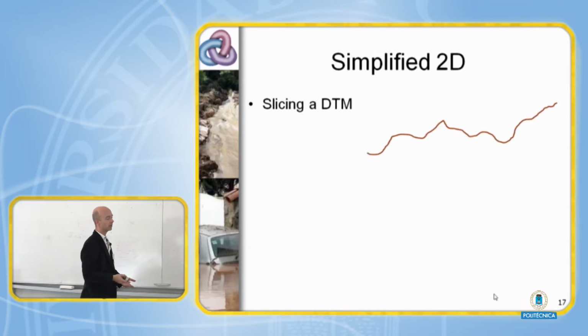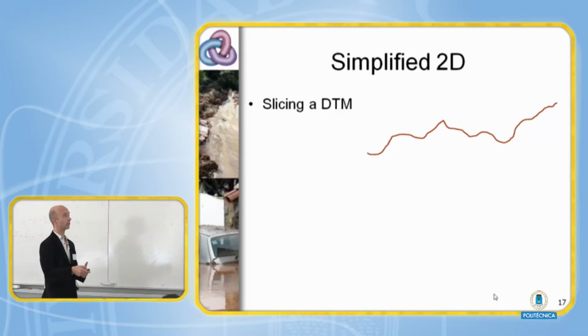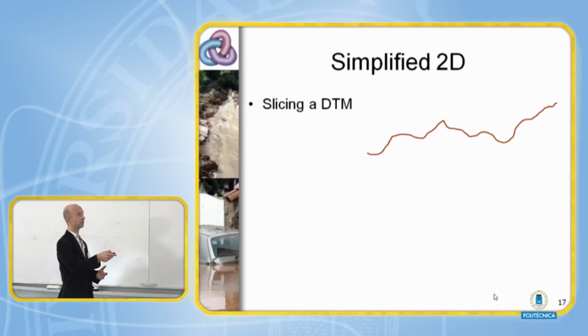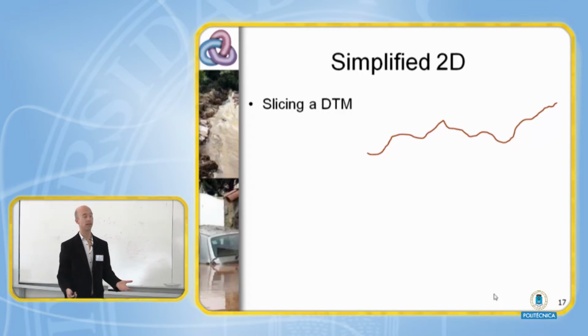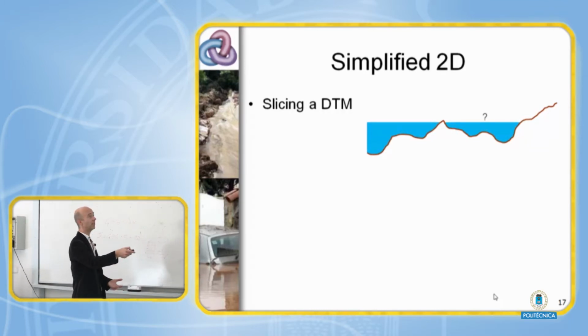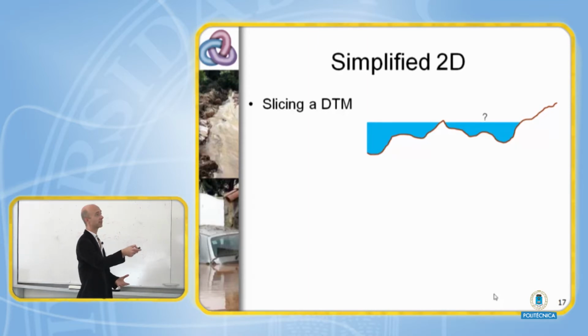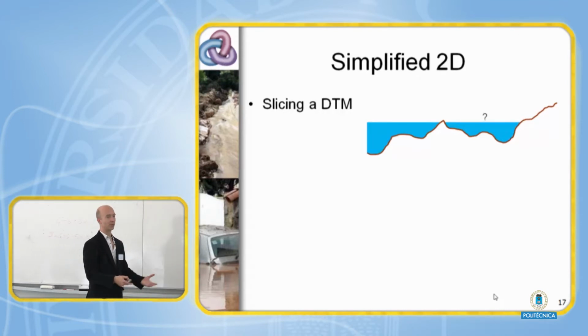So this is a little bit inspired by the previous step where you have set resolution. So let's assume that this is the bathymetry of one grid cell, and you start filling the water. It starts filling, but then suddenly you start seeing water in the second basin, whereas that could not be there in reality unless this barrier has been overtopped. Well, if you don't want that, you need to go to a higher resolution model.